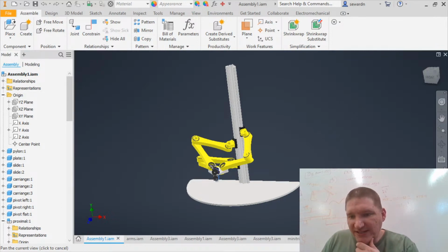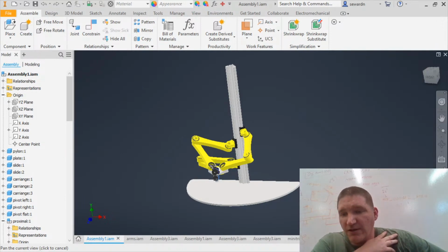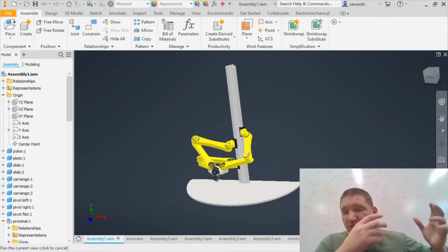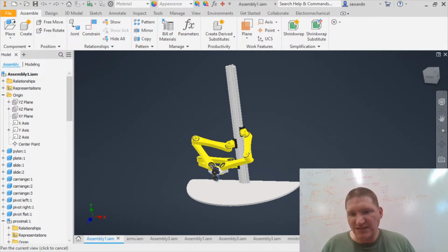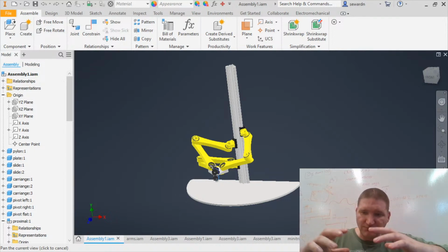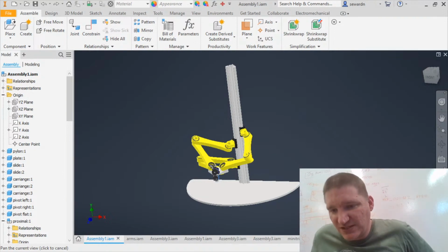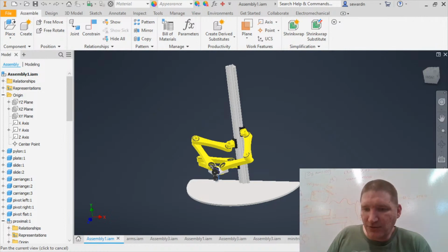Tommy Thorne asked, would there be a significant twisting force on the monorail? And yeah, I mean, not significant, not more than a rail could handle for sure with what I'm going to build it for. But you should bolt it down. Anything that long, on the order of meters, even if it's made out of metal, is pretty twisty. If you do the calculations, it doesn't take much to get a little bit of a deflection. They can handle the forces, but would it actually bend down and cause some problems in positioning? I don't think so, not a whole lot, but it would be a factor. So might as well bolt it down and not make it a problem.